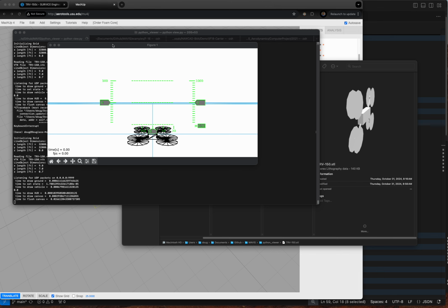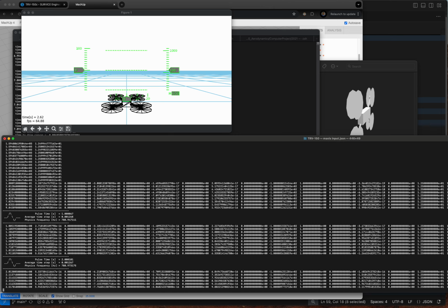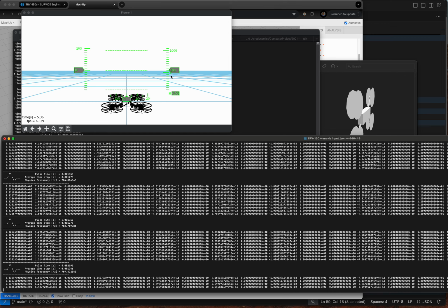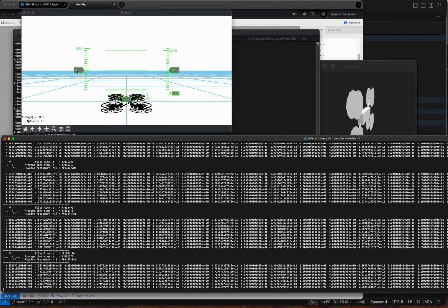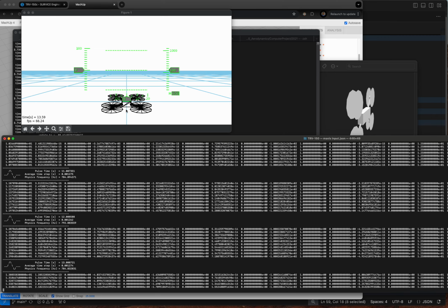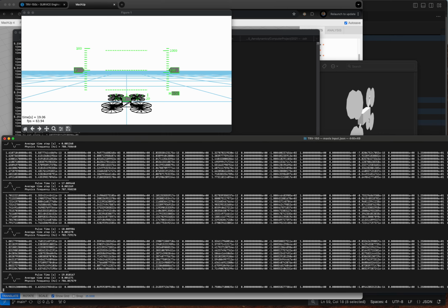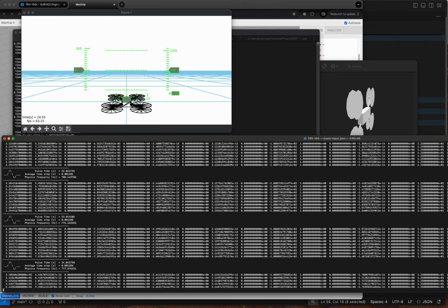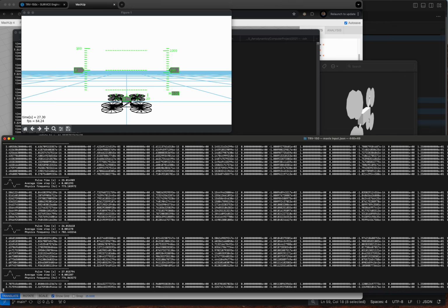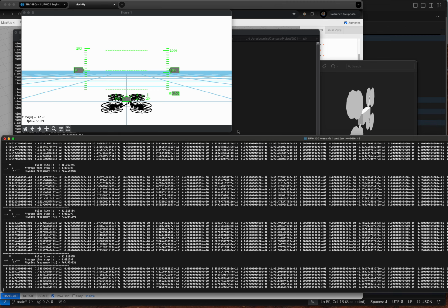And now we're going to watch this vehicle as we run MAVIS down here, and it will run for a whole minute. Okay, so we initialize this in the input file to start at 100 feet in altitude. On the right hand side here is altitude, and this is our velocity over here. Now we set this to be perfectly trimmed. So each of these rotors is outputting 12.5 pounds of thrust. It's choosing the RPM. All of the torques are perfectly canceling, and so it turns out this vehicle will sit here and hover forever until machine precision adds up. We get enough air for it to start moving, but that'll take a while. So this is just perfectly trimmed as we have it. So that's kind of boring.